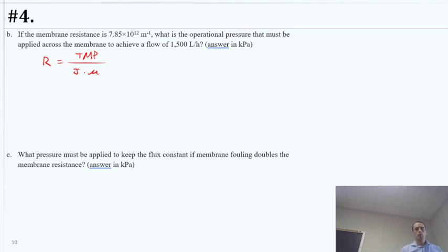Okay, so we know the viscosity. We've been using the same temperature for the exam. This is at 20 degrees Celsius. This was 1.002, excuse me, 0.002. A few minutes ago I wrote 0.02, so I might have one or the other of these slightly off. You guys didn't catch me. Hopefully I just wrote it wrong and did the calculations correctly in Excel. But please let me know if you see that I've done it wrong. Should be 0.002.